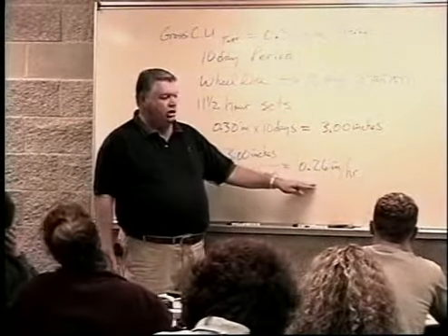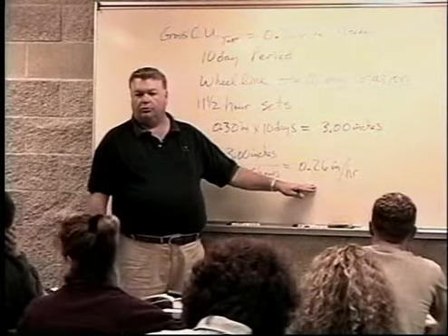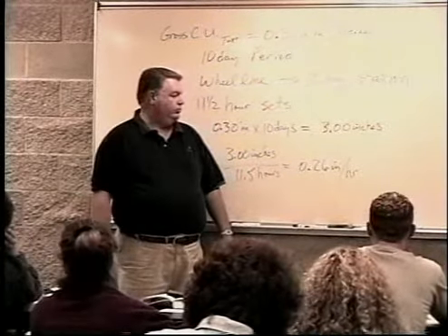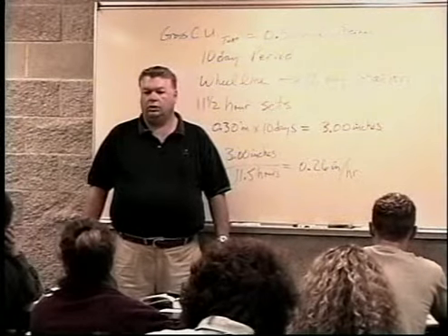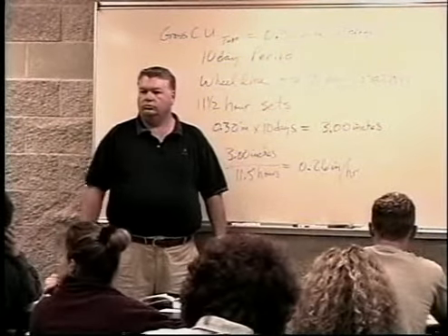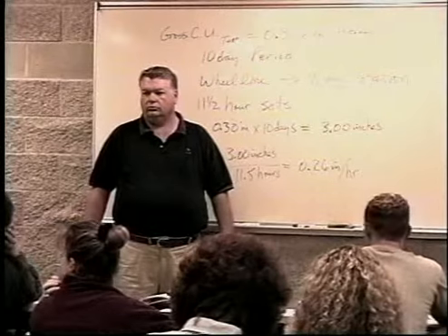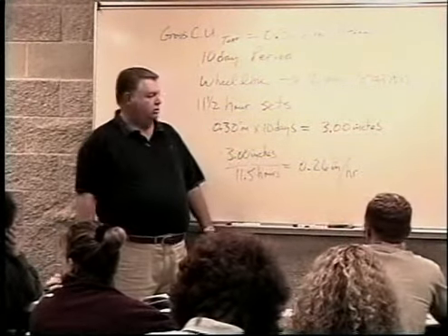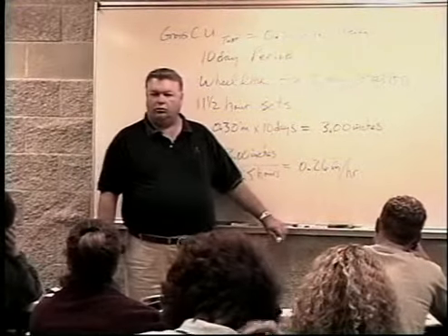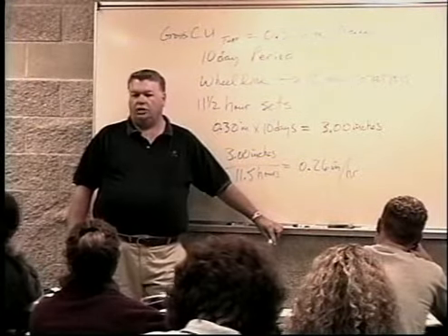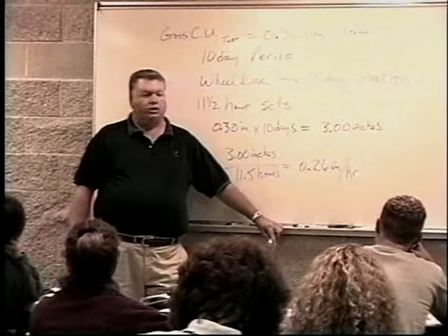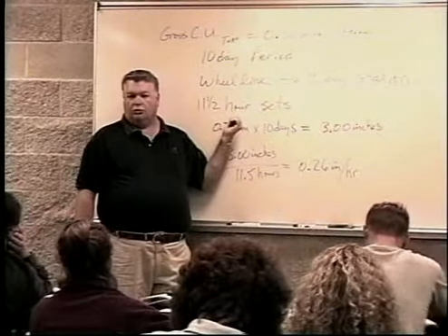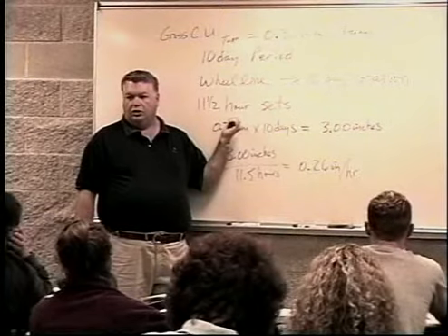Now, from here, we can calculate the total gallons per minute by knowing how many sprinklers we're running on the line. If the ground couldn't take that much water a minute, what would you have to change, like your water window? You'd have to water longer? Okay, the question is, if the ground won't take the water that fast, what could we change? And one thing we could do is lengthen the time of set, isn't it? So we put less water on per hour. That would be one solution.